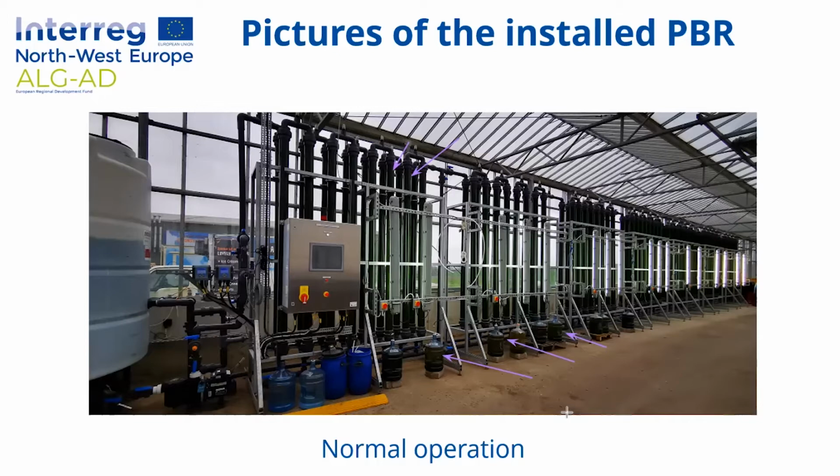And obviously you can see in this particular image as well that the full serpentine reactor is up and running. You can spot that there's about half a tank full in the dark tank there. So this would be operating at something like about 5,500 litres in this reaction system. So if we harvested the whole thing, in this particular case, we would get something like about 10 to 20 kilos of algae out of this particular reactor.